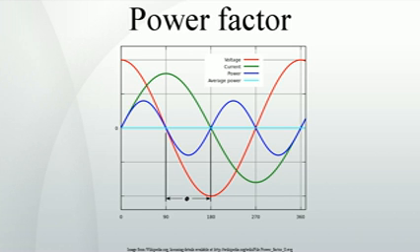Power factor correction may be applied by an electric power transmission utility to improve the stability and efficiency of the transmission network. Individual electrical customers who are charged by their utility for low power factor may install correction equipment to reduce those costs. Power factor correction brings the power factor of an AC power circuit closer to 1 by supplying reactive power of opposite sign, adding capacitors or inductors that act to cancel the inductive or capacitive effects of the load, respectively. For example, the inductive effect of motor loads may be offset by locally connected capacitors.